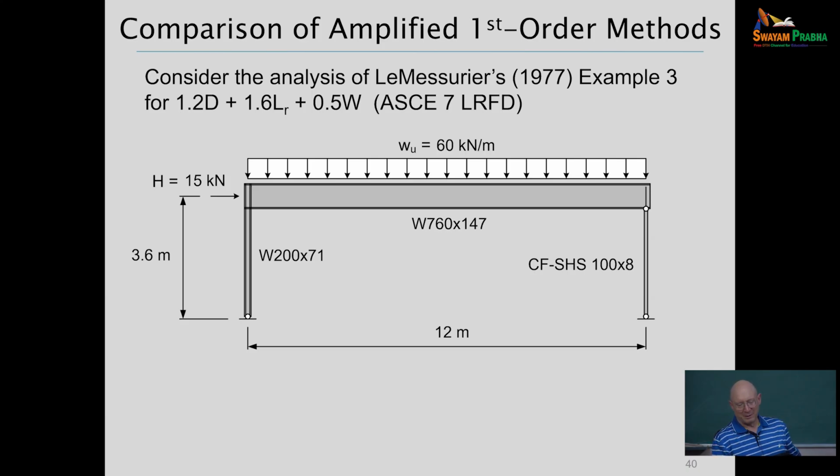We've got a reasonably lightweight wide flange column on the left, reasonably deep roof girder on the frame, and this market shed, so to speak, LeMessurier would say, on the right is storefront, so we have a very light HSS column there, and we're going to idealize that as a leaning column in this analysis.